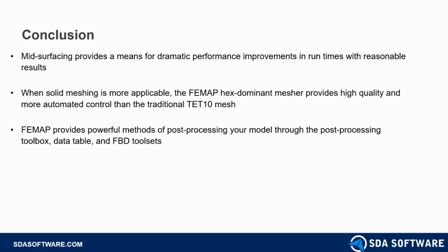The cool thing about FEMAP is it unlocks so much capability that you do not have with Inventor Nastran, because the core solver can be disconnected in Inventor Nastran and used directly with FEMAP. So just adding FEMAP unlocks tremendous capability, including all of that meshing that we just looked at, and the hex meshing, which is hex dominant, that includes pyramid elements and everything else. All of that is supported in Autodesk Nastran.